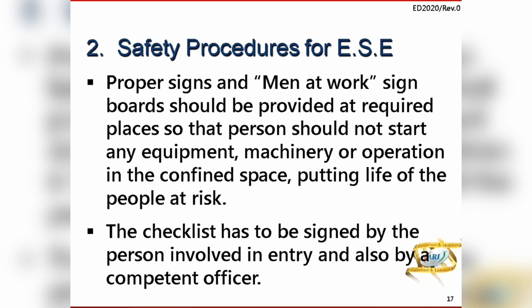Proper signs and men-at-work signs should be provided at the required places so that no one starts any equipment, machinery, or operation in the confined space which will put the lives of people there at risk. The checklist has to be signed by the persons involved in the entry and also by the competent officer.